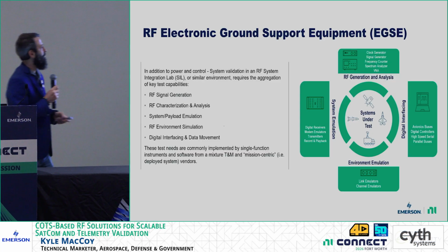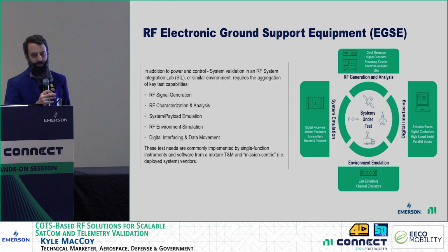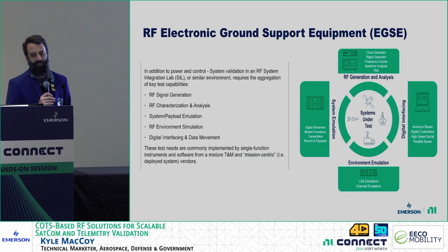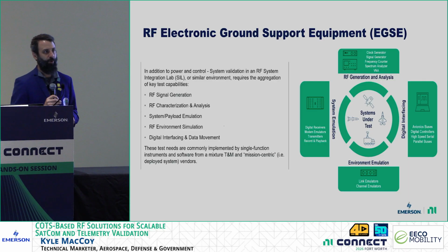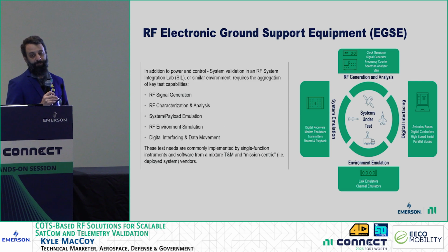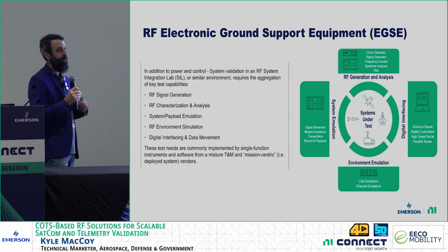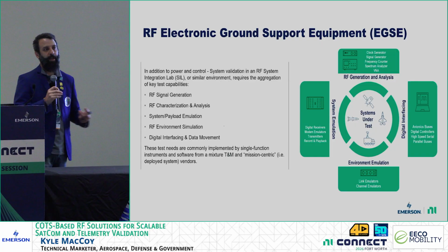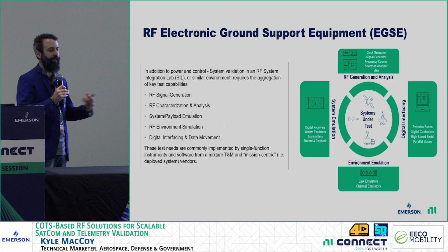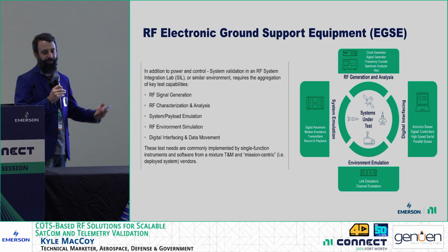So typically there's basically four domains that you would have to look at for doing this kind of EGSE testing, for electronic ground support equipment. You'd look at RF generation and analysis for your parametric test to make sure that your components in your system were working properly. You would want to be able to do some system emulation to make sure you had an endpoint that could match, and a lot of times that would be handled with some sort of golden dot or a system that was standing in for the receiver or transmitter of your system.